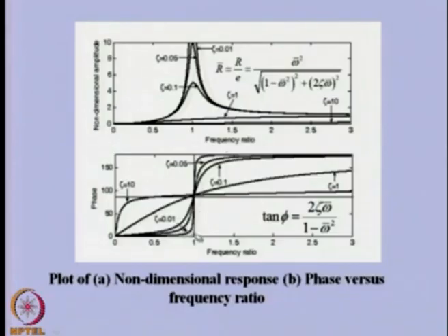So, there is a change in the phase at critical speed. You can see a change of the order of 180 degrees. The meaning of that is the response changes its phase with respect to the force, and there is a change of 180 degrees. That means the unbalanced force which was outside becomes inside, toward the center of rotation of the shaft, and because of that it tries to pull the rotor toward the bearing axis, and because of that we have smaller displacements as we are going toward the high frequencies.